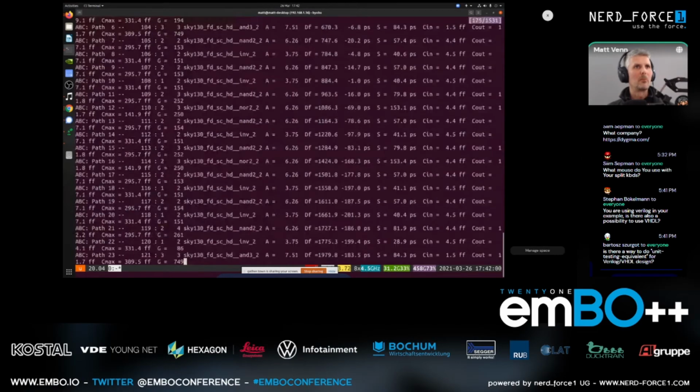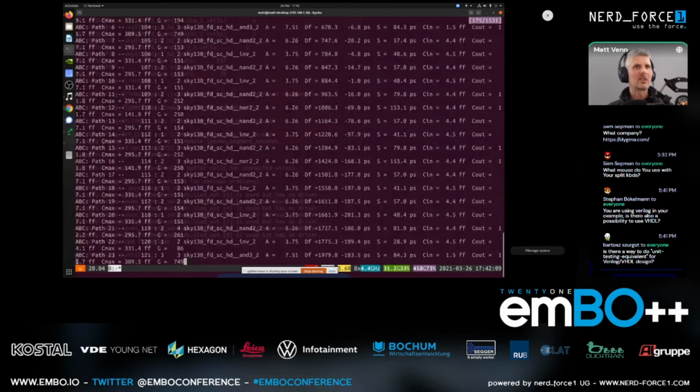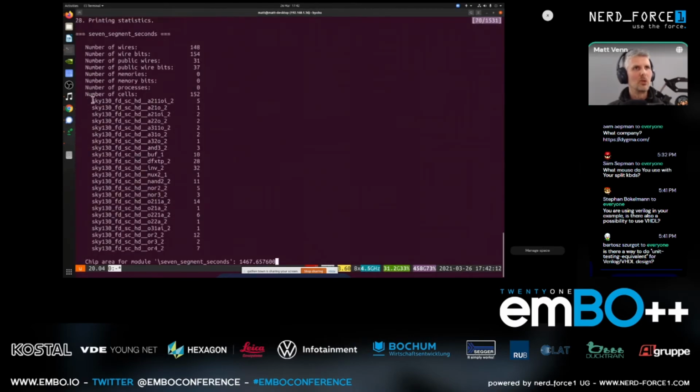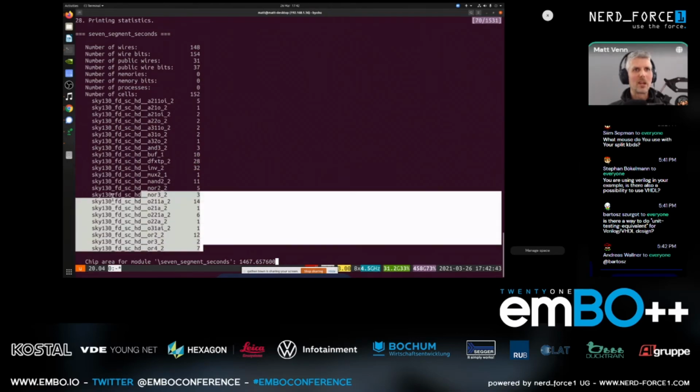And we start getting all of this log output. Here we see output from Yosys describing what logic it needs. And then a bit later on, we can see how that gets mapped into the actual number of cells that we need. So to make that 7-segment demo, we need 152 standard cells from the PDK, including 28 D-type flip-flops. We needed 24 flip-flops for the 16 million counter, and we needed 4 for the count up to 9 for the seconds counter. So 24 and 4 is 28. And then we've got OR gates and other OR gates and lots of different types of OR gates.